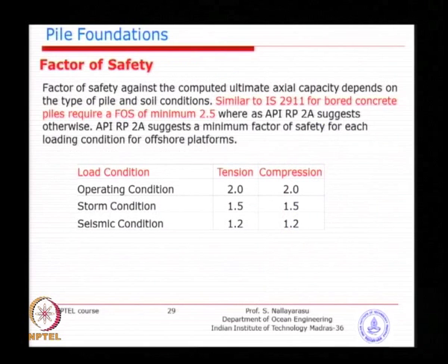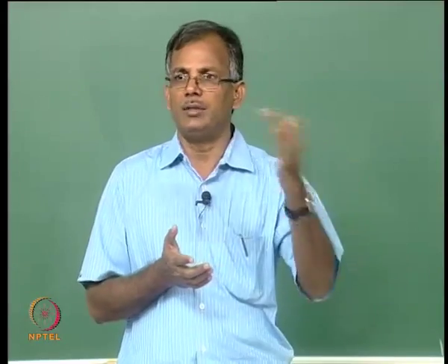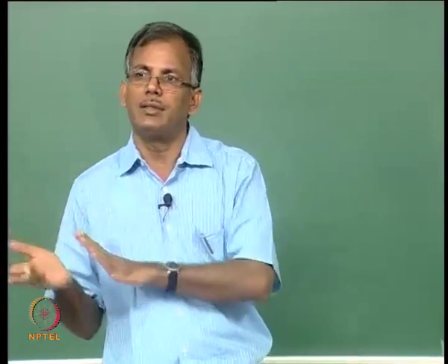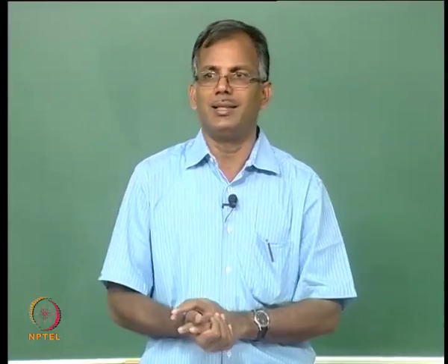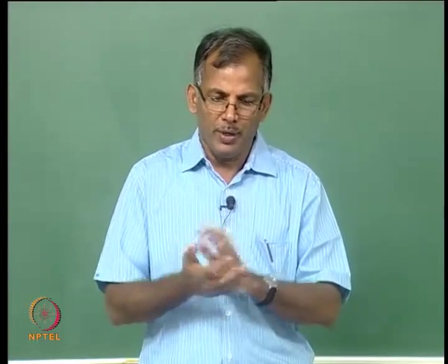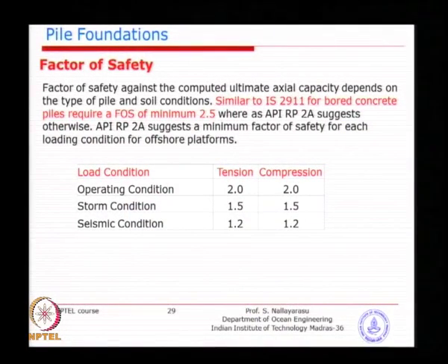So besides the conventional methods of field testing and laboratory testing, CPT methods are also recognizable, which can be used. Now the last one, we have seen the capacity calculation involves so many uncertainties, starting from borehole and then soil sampling and strength assessment, classification of soil and then to establish the friction and end bearing.